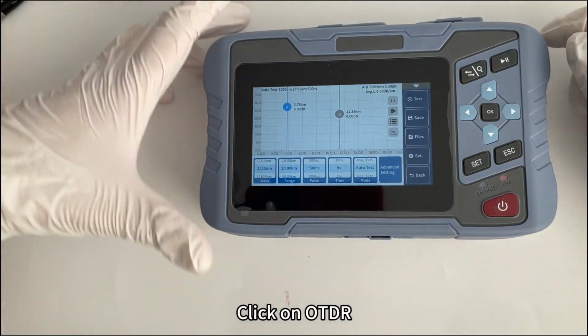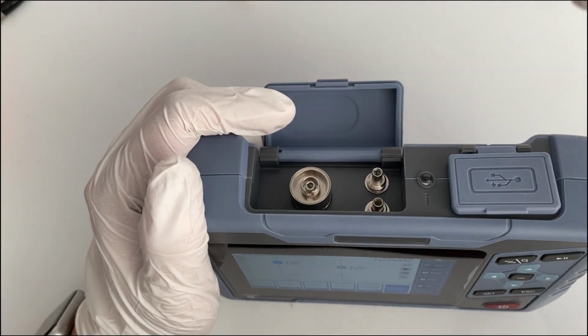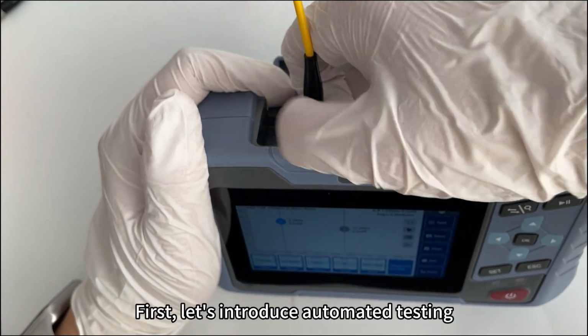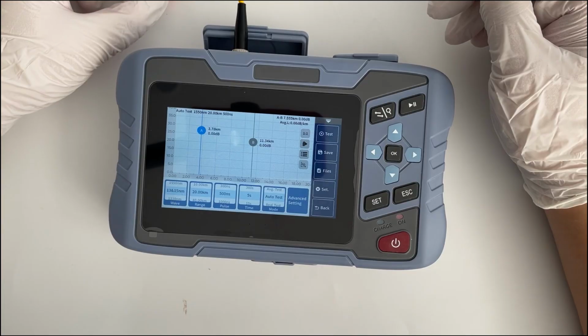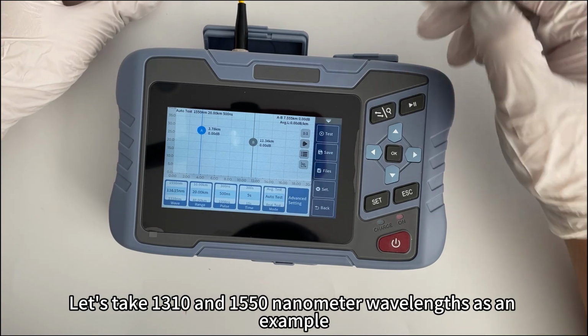Click on OTDR. Accessing the fiber under test, 2 kilometers plus 5 kilometers by side light. First, let's introduce automated testing. The test wavelength needs to be selected during automatic testing. Let's take 1310 and 1550 nanometer wavelengths as an example.